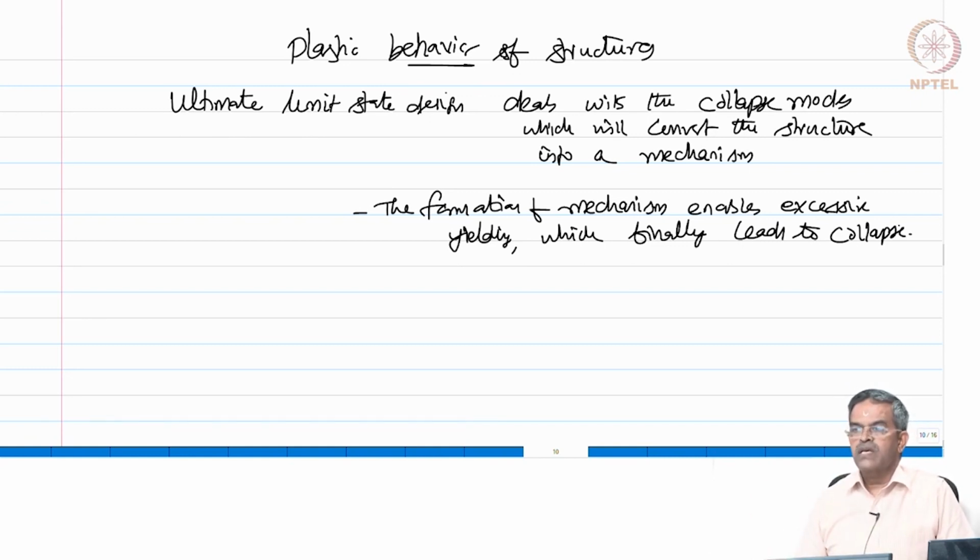We all know, friends, that steel is a very common construction material which has got enough ductility. Looking at the stress strain curve of steel, it is evident that the material has got good capacity beyond the first yield. Therefore, any design procedure which limits the strength till the first yield, like an elastic design, is not a good design procedure. So, the material strength beyond yield, which is having enough reserve value, is not utilized. So, there should be a design procedure which utilizes this excessive reserve strength beyond yield value, is it not? The load carrying capacity can therefore be increased because of reserve strength. But however, this does not mean that the structural capacity should be extended beyond a value that results in a catastrophic failure.